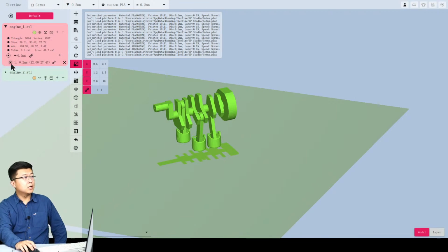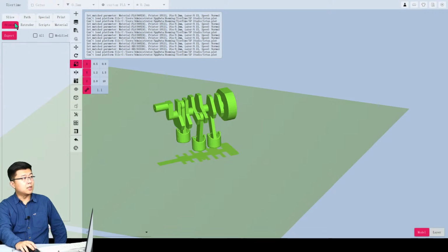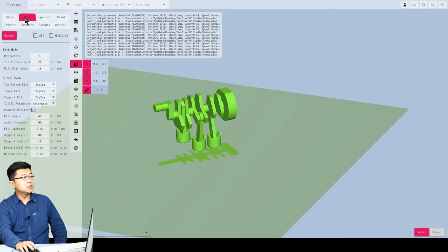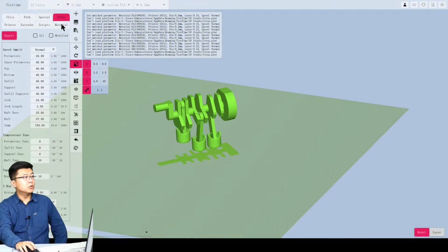As you can see, I have a gear icon beside this section. Now I click this gear icon, and it opens up individual print settings for just this section I just chose. I can set the perimeter, the layer thickness, and the path width, all just for this section.